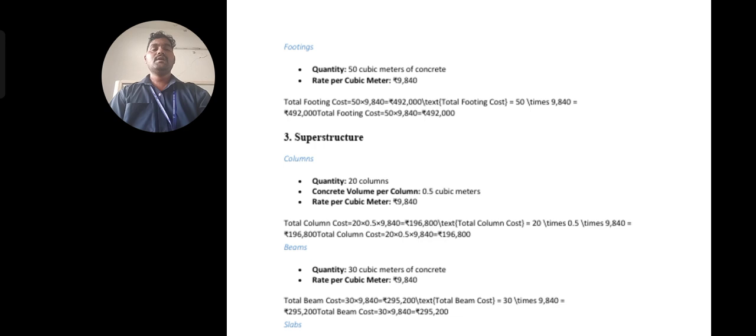Generally, for example, for 1 cubic meter, 500 clay bricks are needed, costing around 10 rupees each, so it is equal to 5,000 rupees needed for 1 cubic meter of brickwork. That is only material. This brickwork also contains mortar in between to make a bond, so here we also calculate the mortar required to make a bond, and the mortar cost, and then the labor cost is included in the total cost.